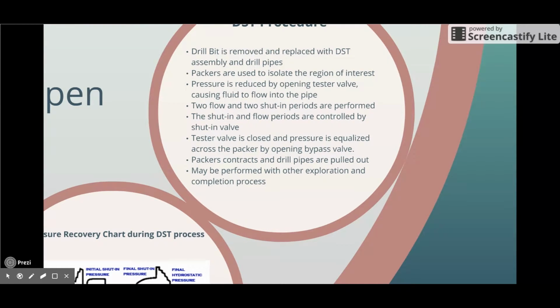The tester valve is closed and the shut-in valve is open during running in hole. This allows the drilling mud to go into the perforated anchor and out from the bypass ports without entering the drill string. The pressure recorders show the pressure due to the mud column height when we are reaching the bottom and setting the packer. After the pipe reaches the bottom, the packer is set.